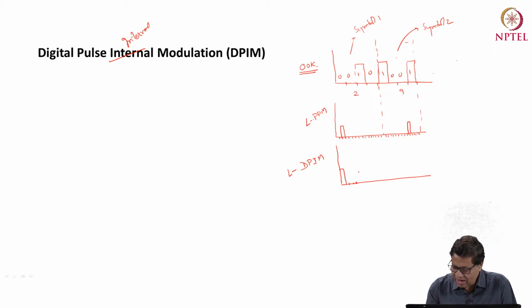And then the second is 9, decimal value is 9, so then it will be 9 plus 1 slots, that 1 is for the guard band, so this will be somewhere here. So this is actually two slots, because the decimal value is 1 and 1 you keep for the guard band. And similarly this will be 9 plus 1, 9 empty slots and 1 for the guard band.